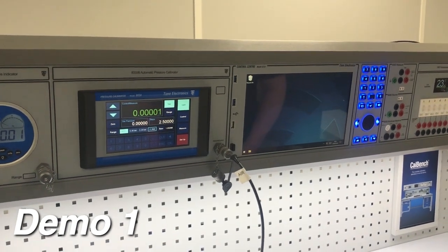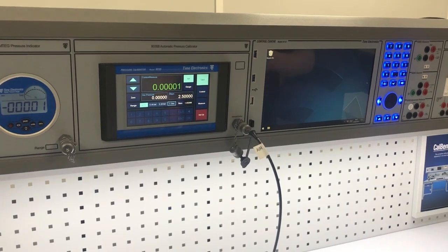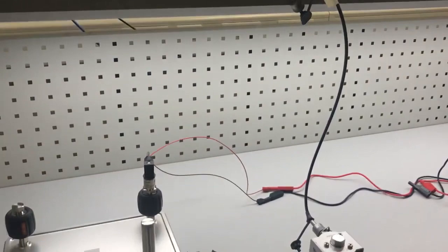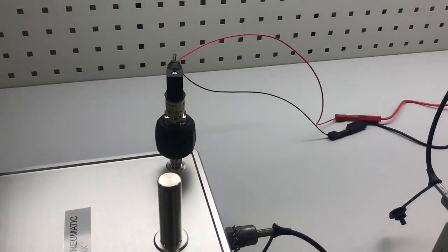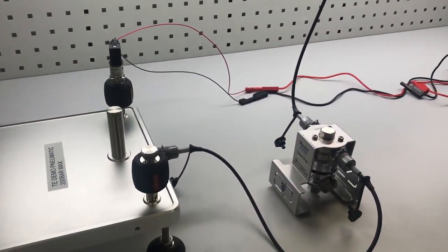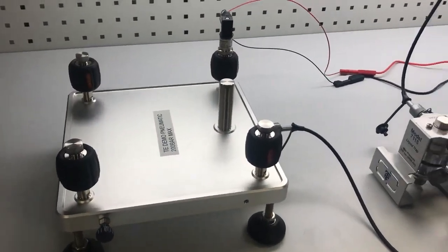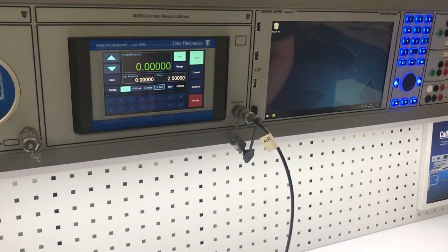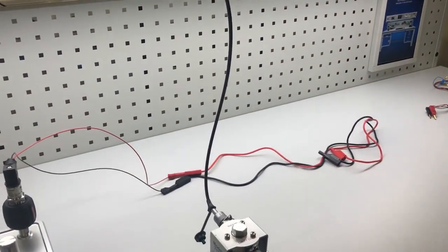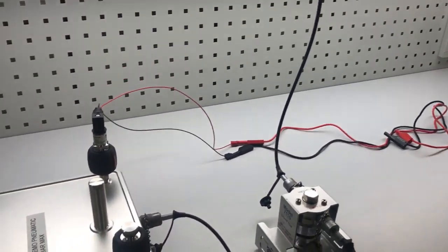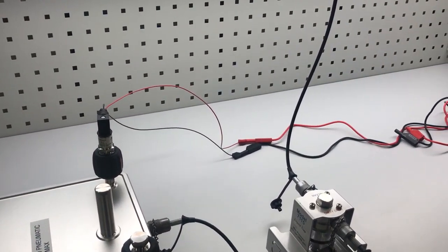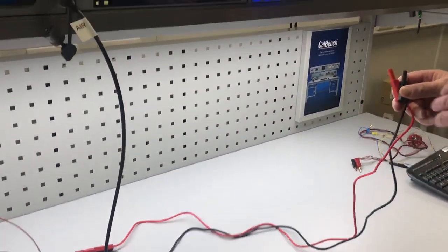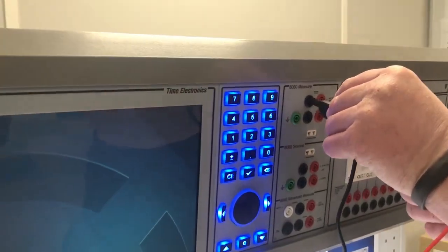Okay, so this is an example of using the manual control applications to check the calibration of this pressure transmitter. We have a 10 bar pressure transmitter fixed into the 4-port manifold, and that's connected from the output of the 8030 automatic pressure calibrator. So on the pressure transmitter that we're going to calibrate, I'm going to connect the 4 to 20 milliamp loop signal to the 8060 measure terminals,